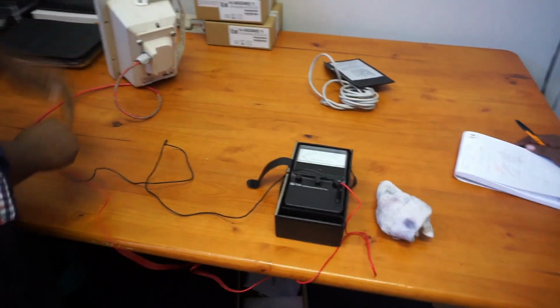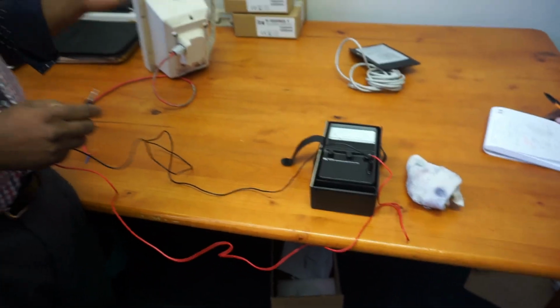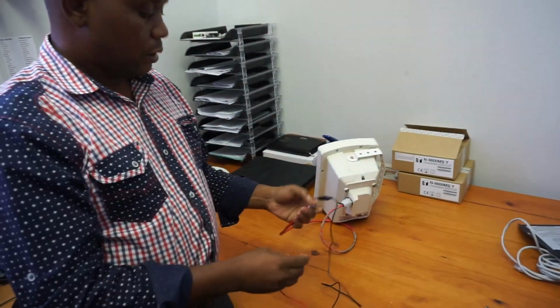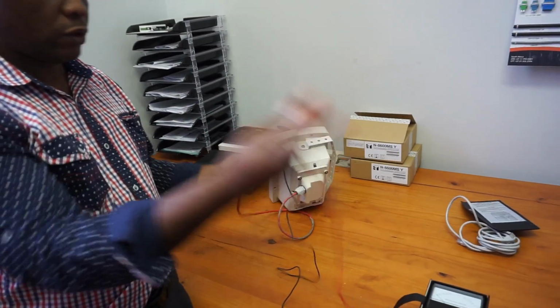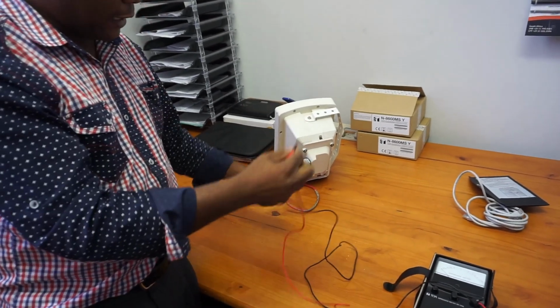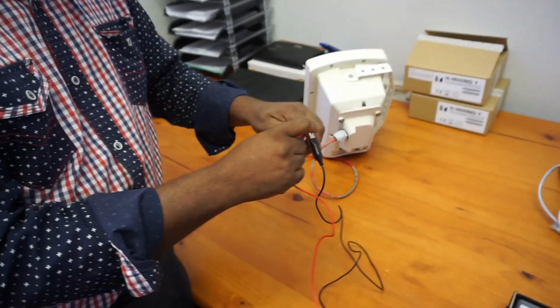Okay, once again, to demonstrate with a short piece of wire, we normally have an open circuit. So an open circuit is what I've done now. I plug in here, there's no reading because the positive is not connected. So this is an open circuit. A short circuit is basically taking this and that together and shorting them out.